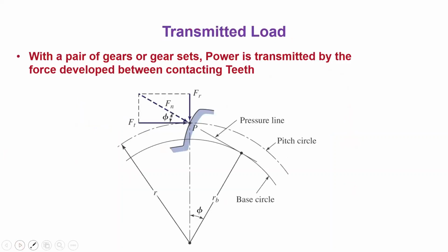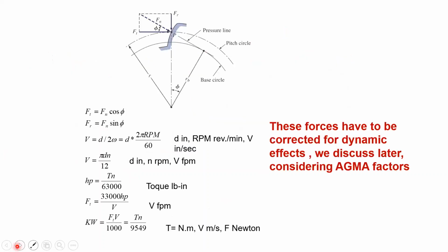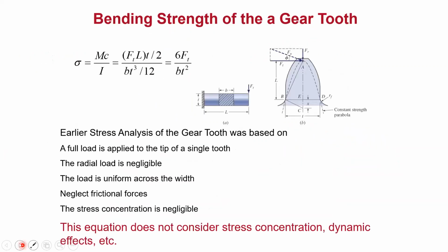And so we need to follow the law of gearing. What I was telling, the law of gearing, you have to follow those things when you're going for a design application. When you're going for the design aspects of the gear, you need to follow this. The very important thing when you are going for a design, what normally we do is we look for a strength purpose. We need to select the gear tooth considering the bending strength.